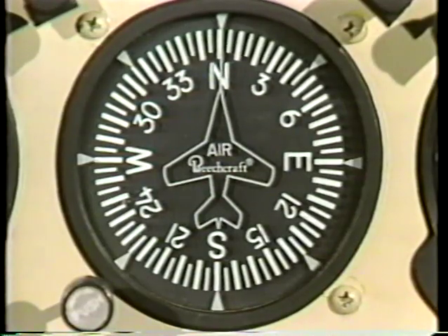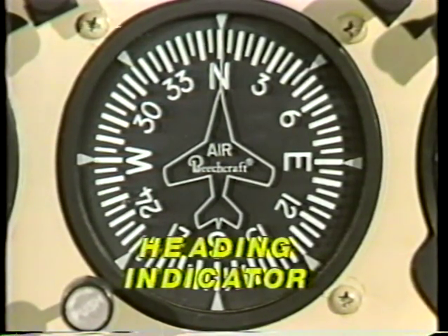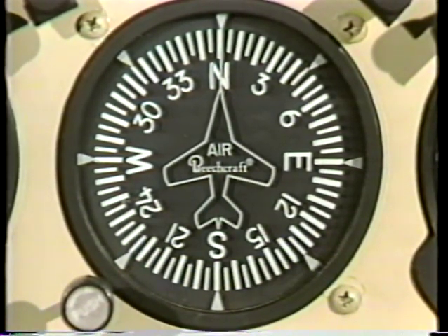The turn coordinator is extremely reliable because of the gimbal structure, and this is the gyro instrument that is usually electrically powered. The heading indicator is the last of the 3 gyroscopic instruments. This is not the airplane's magnetic compass, which we will explain shortly, but rather an instrument designed as an easy-to-read indication of direction, free from magnetic compass errors.